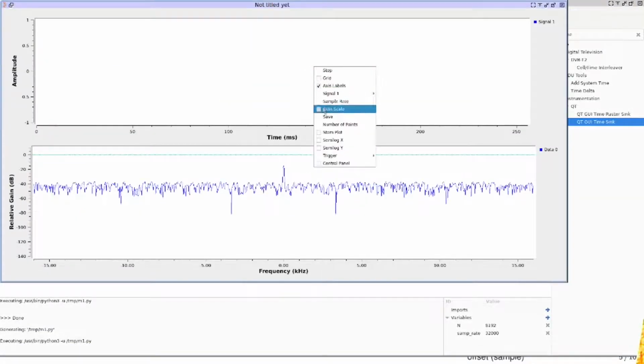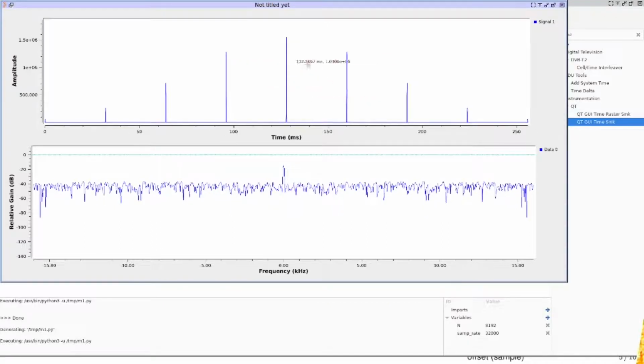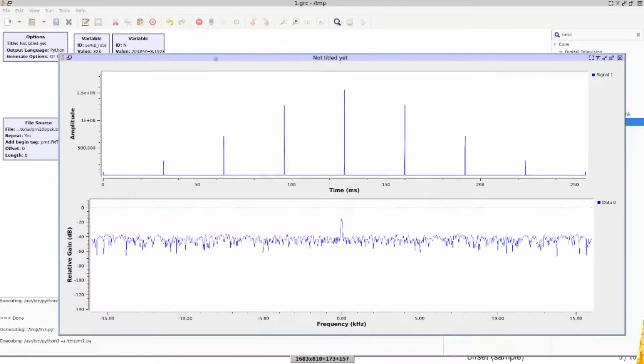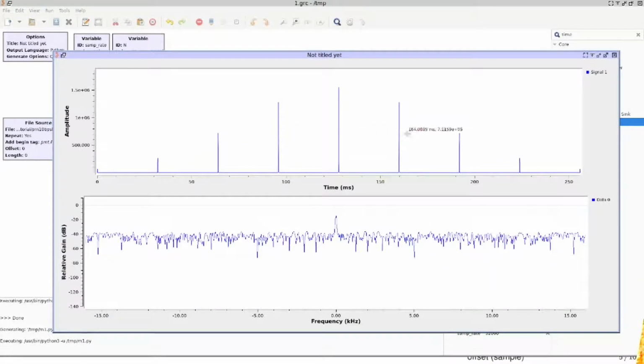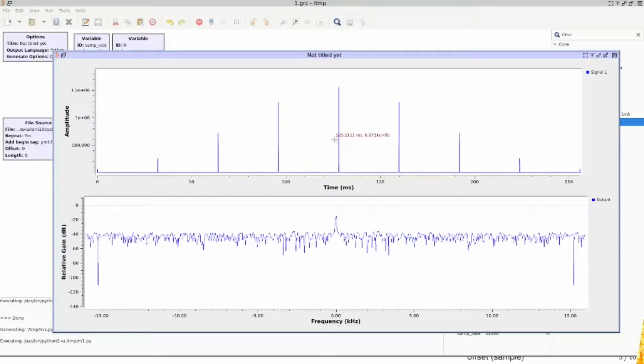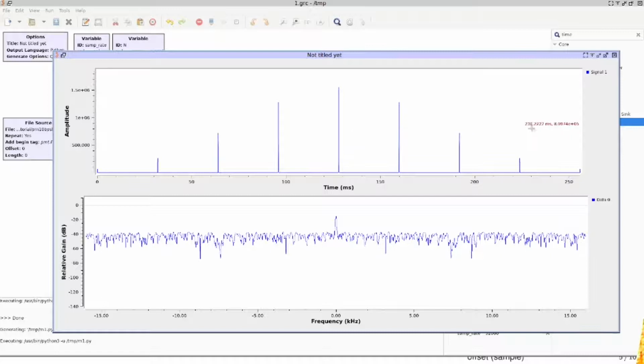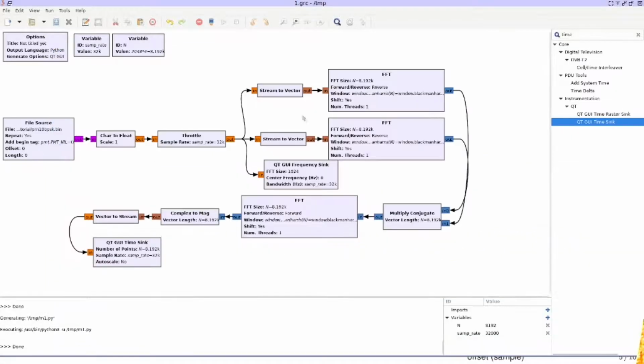and if we auto-scale, surely enough, we see here that whenever the pattern repeats, because it's only a 10-bit long pseudo-random sequence, if we take a longer Fourier transform, so if we take the autocorrelation over a long enough duration as the file is repeatedly read, we see here that we have a repeated pattern. This validates the fact that we have indeed generated in our FPGA a pseudo-random sequence.